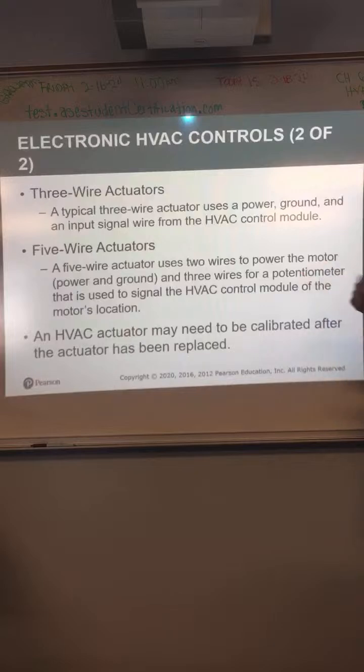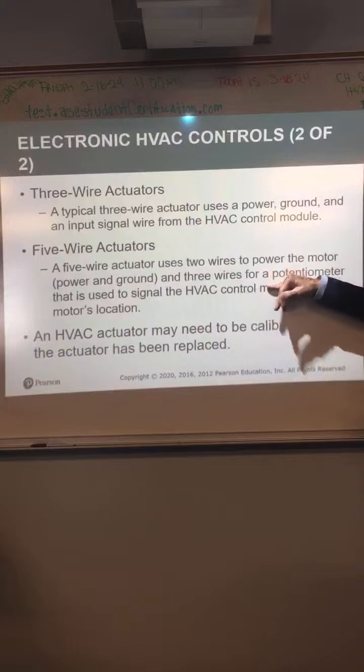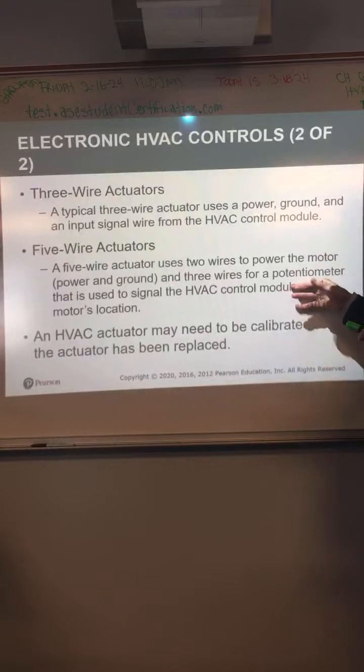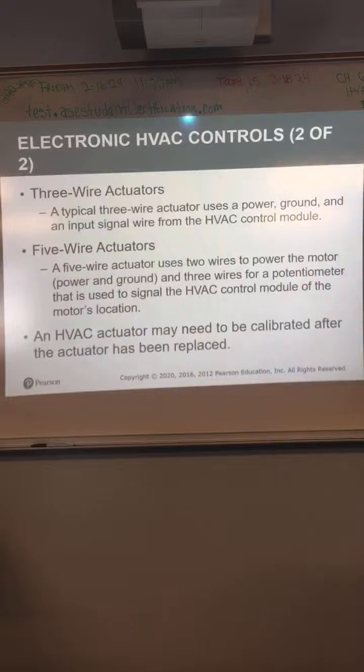It's going to see the signal from the control head, and then it's going to say, okay, did it go there? And if it didn't, it's going to tell on it. What code would that be? It depends on the car and which actuator it is. Okay. But they're going to be typically a B code, which is body controller. Okay? C is for chassis, P is for powertrain. The codes are all structured to where you know what each one is, as far as what system it's related to. Right.